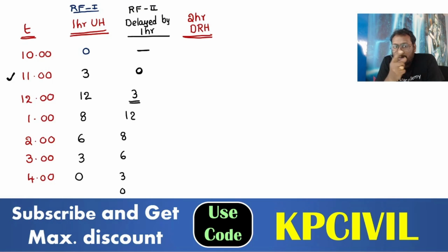Because 1 hour UH for rainfall 1 and 1 hour UH for rainfall 2, we are adding both. It is 2 centimeter now, not 1 centimeter. 1 centimeter for rainfall 1, 1 centimeter for rainfall 2. So it is not a unit hydrograph, it is a direct runoff hydrograph, as the depth of effective rainfall is 2 centimeter.